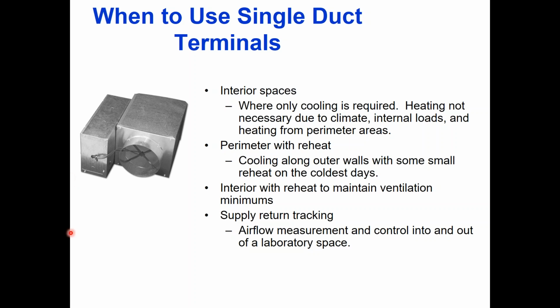Sometimes we'll do supply and return tracking systems. By that, I mean there'll be a VAV terminal like this on the supply duct, and there'll be another one on the return duct for that same room. That's not super common, but you'll see it in hospitals and in laboratory environments where they really care about the pressurization control in between zones.